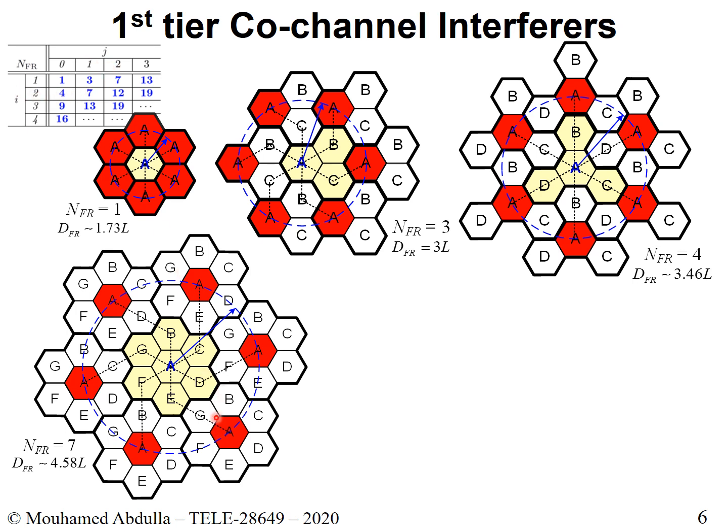In here, what I used is 1 and 2. So I move by i, by 1. I turn counterclockwise and I move by 2. And I found this one. For this side, I move by 1. I turn counterclockwise and I move by 2. I find this one. For this next one, I move by 1. I turn counterclockwise and I move by 2. I find this one. And the same. So you see the trace of how we applied the algorithm to find the co-channel interference.